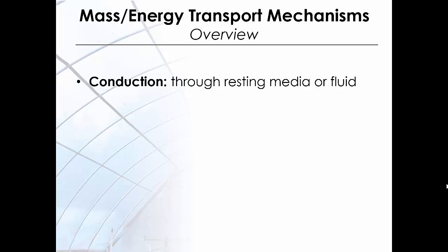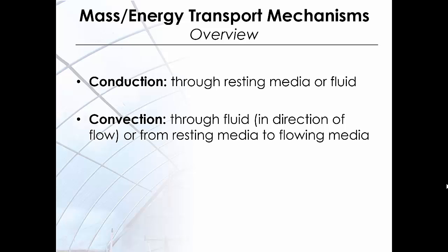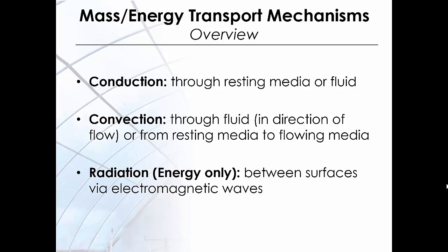Energy transfer through conduction, which is the transport through a resting medium, solid, or through a fluid not in the direction of the flow. Convection, which is the transport through a fluid in the direction of the flow, or transport from a resting medium to a moving medium. Radiation, for energy only, which is the transport between surfaces of opaque bodies by electromagnetic waves through a transparent medium.